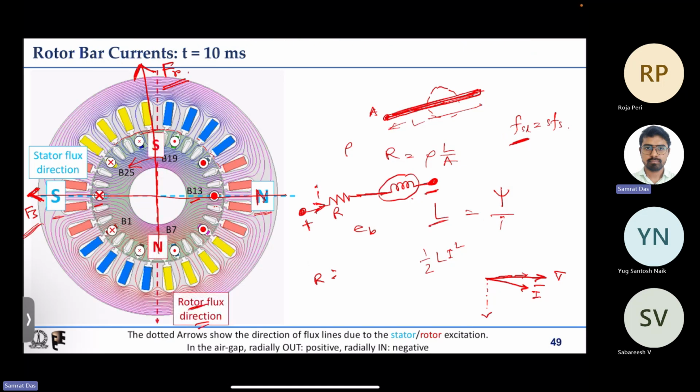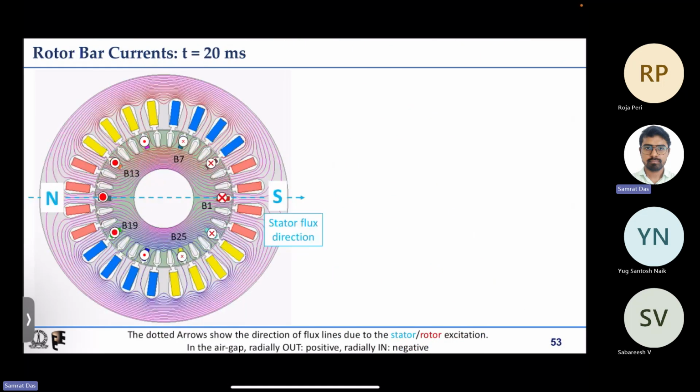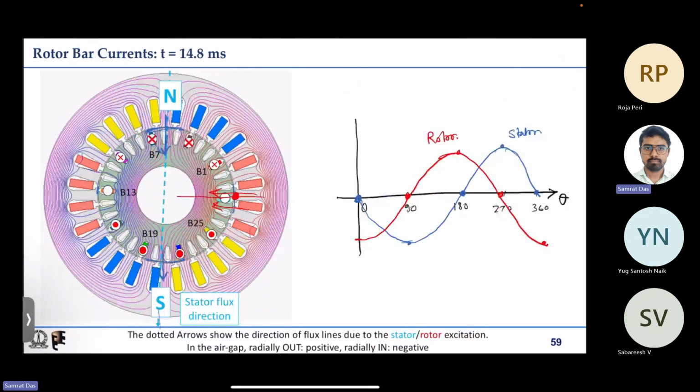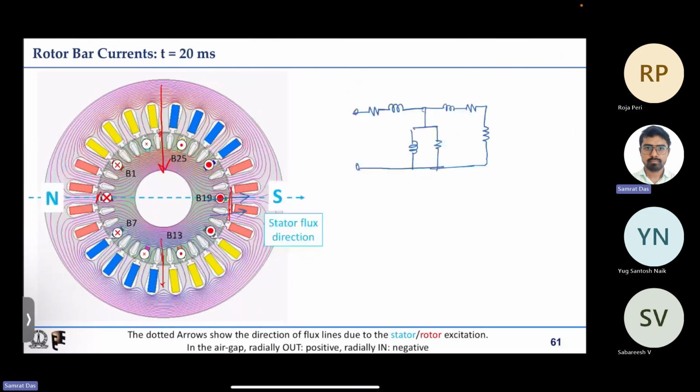So the electrical equivalent circuit of the stator for induction machines can also be indicated by some induced EMF, say E1, and we are giving some supply, say V in, and there will of course be some resistance of the stator winding and some leakage inductance of the stator winding. What do we mean by leakage inductance?